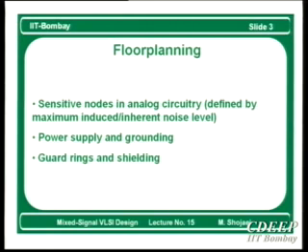Okay, so you may have heard about floor planning. When you want to make a layout or physical design, you want to know where you want to keep your modules. This is called floor planning. You have a set of modules, black boxes. You want to arrange them like a puzzle in such a way that the performance of the circuit will be minimally degraded. So this is called floor planning.